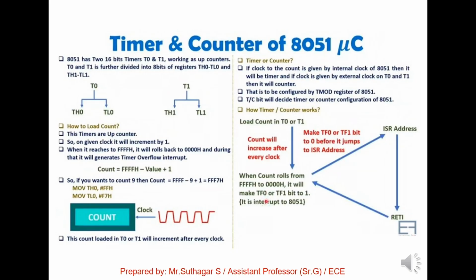So whether it is a timer or a counter, as I told earlier, when you make use of the internal clock of 8051, it will act as a timer. When you make use of the external clock, it will be acting as a counter, right? So for that we need to configure the TMOD register that we have discussed earlier, and there we will be choosing whether we are going to make use of that as a timer or a counter.